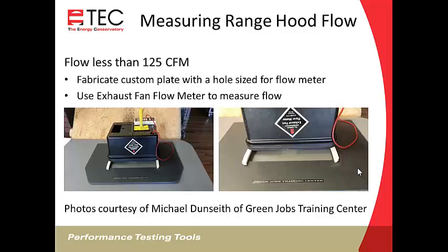exhaust fan flow meter. And these photos were courtesy of Mike Dunseth with the Green Jobs Training Center, and he fabricated a really nice one for his training center there that'll fit their range hood. And you can see he connected some pieces on the side here so the exhaust fan flow meter will fit tight to that. So when you pick up the exhaust fan flow meter, that plate will be attached, and it fits really nice into that range hood opening, so you can get a really accurate measurement through that range hood.